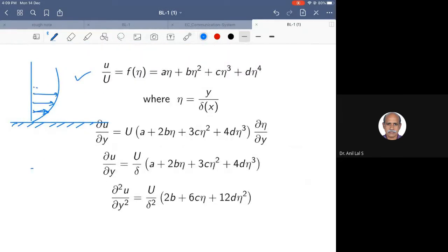So this is the velocity, the potential velocity, and from there onwards it is like that. Here we have no slip: U is equal to 0, V is equal to 0. So we take an approximate polynomial variation for this velocity profile in the boundary layer.